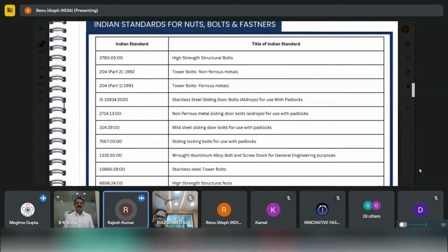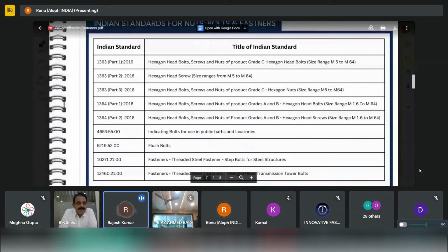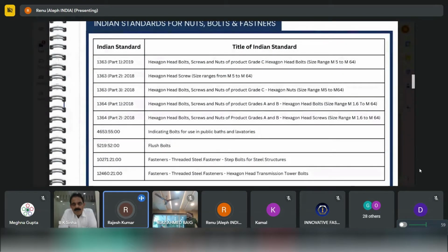Thank you. Hello, Mr. Sriram. Sorry, my name is Rajesh. I'm calling from Daichi Fastener, Neemrana. Sir, we are making one bolt, M8 into 1.25 size, for Maruti Suzuki. As per your standard range, we are falling in this category for 1364 part 1 also, hexagonal head bolt. But the point is, the shank dia and across flat of my customer design are not matching with the BIS standard.